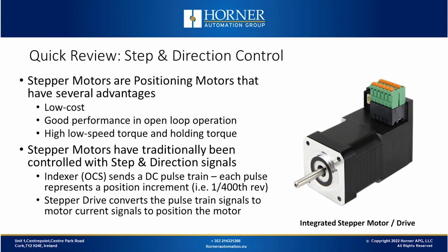Stepper motors are positioning motors that have several advantages. First, they have a low cost. They have good performance when used in open loop operation, which is how they're usually used. That's partly because it has good low speed torque and good holding torque. Today, you can control a stepper motor over a network with CANopen or Modbus TCP, for example. Traditionally, stepper motors have been controlled with step and direction signals, however.